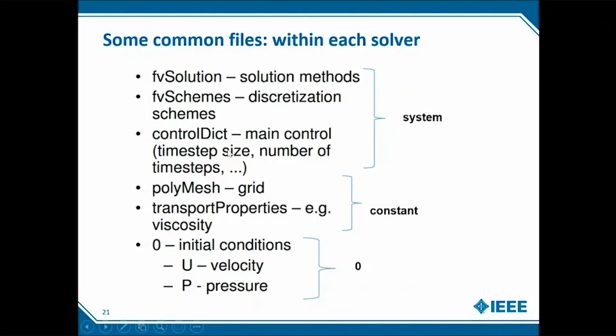So you have to define your time step. What is your time step, number of time steps, how long you want the simulation to run, and what are the different discretization schemes. So we just saw some of them, for example, forward, backward, etc. So which scheme you want to use for your solver. And finite volume solution is basically, so now you have your linear algebraic set of equations, you have to solve them somehow. So what particular numerical method will you use? Will you use Runge-Kutta, or will you use any other numerical method that you know? So all these settings have to be done.